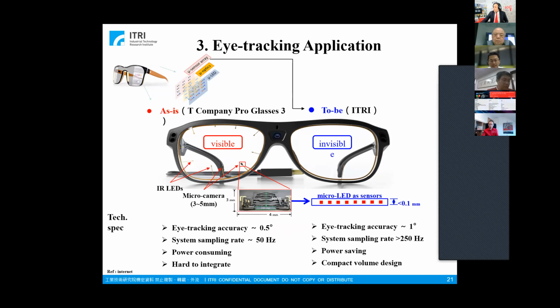On the right side, another eye tracking technology can achieve very high frame rate and ultra-low power consumption, overall at least 5 times enhancement compared to traditional eye trackers. The IR micro LEDs work both as illumination and sensing functions and are mass transferred onto the surface of the glasses. Their size is smaller than 5 micron, which keeps the glass transparent and clear. It will not block line of sight. The point is no ID design issue needs to be addressed anymore.